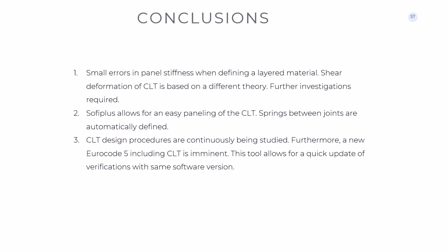We are expecting a new version of Eurocode 5 where CLT will be included. It will be interesting to see what they say, and also whether the industry will be interested in taking this kind of verification into their software, because of course it will be integrated, and it will be a better solution.